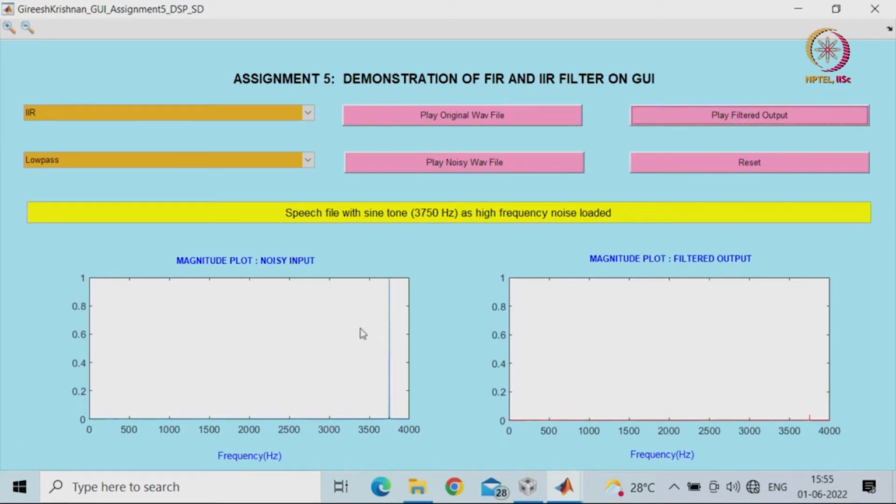So, you have seen the peak frequency which got added has changed to approximately 3500. The scale has not been normalized. I have expanded it, and this was the output. So, this eliminates the higher frequency component present, and it is allowing the speech to come out clean.